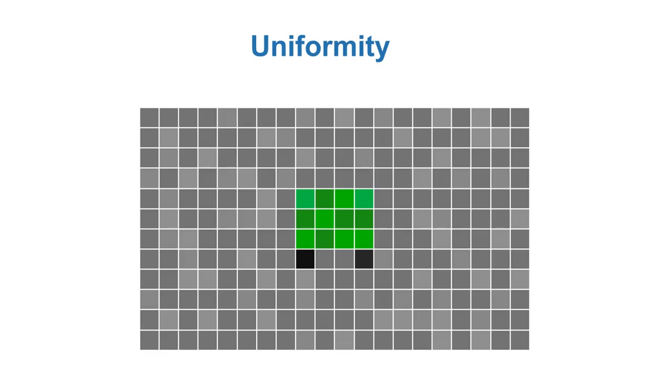Uniformity is another property of vision sensors. For CCD sensors, where only one readout's electronics is used, the uniformity is inherently better than that for CMOS, where small differences in the electronics for each pixel affect the photon-to-volt conversion. However, today's CMOS sensors also have quite good uniformity, despite its earlier issues.